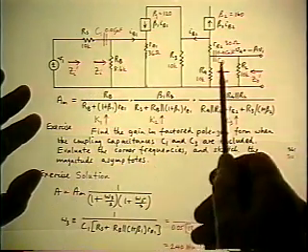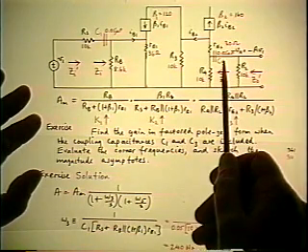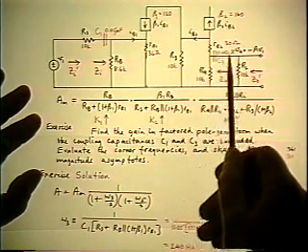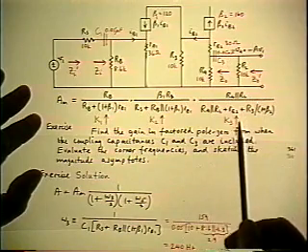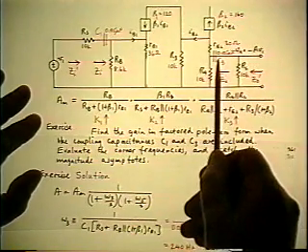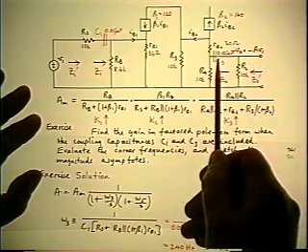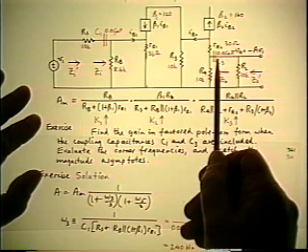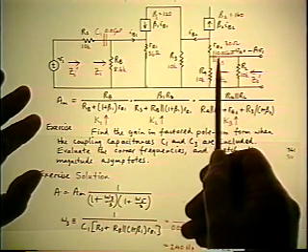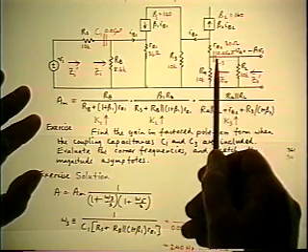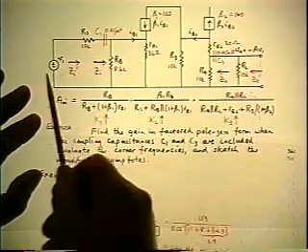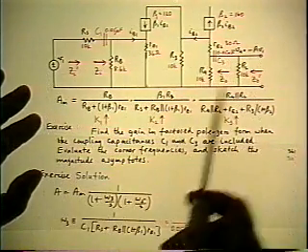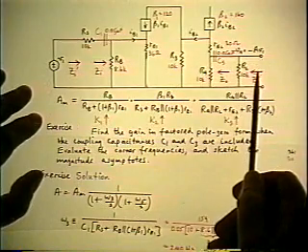Now you do the same thing for the C3. In fact, it's in a similar position. So you can tell in advance you're going to get an inverted pole from it, but no inverted zero. If only because at zero frequency, the C3 opens up and disconnects the output from the input, so the gain is going to have to go to zero at zero frequency.